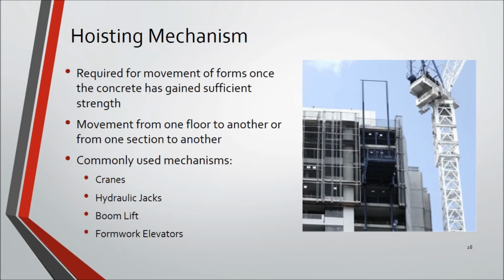Hoisting mechanism is required for movement of forms once the concrete has gained sufficient strength. Commonly used mechanisms are cranes, hydraulic jacks, boom lift and formwork elevators. The adjoining figure shows a formwork elevator specially designed for a building.